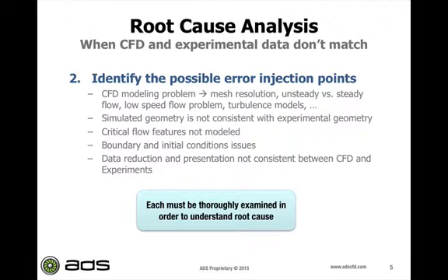If we are not looking into this geometry issue, no matter what we do in the turbulence model and improve our simulation, if it matches the data, you're lucky, or rather, I think you're unlucky now. You no longer have a tool you can use for prediction, because if you run the wrong geometry, there's no chance for you to match that data. But if you do match the data, you're walking down a very dangerous path.